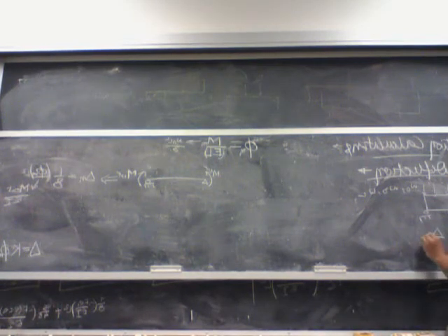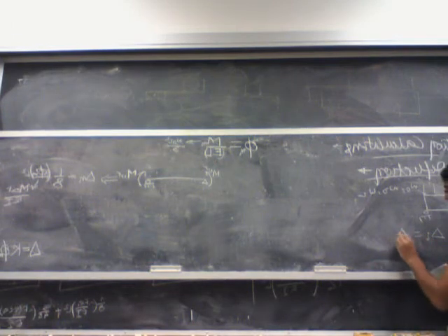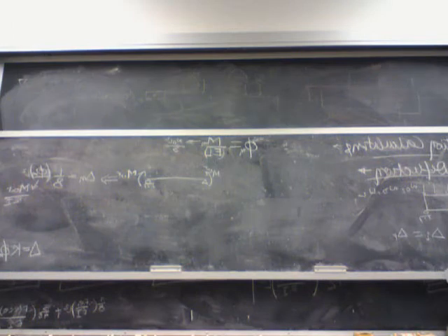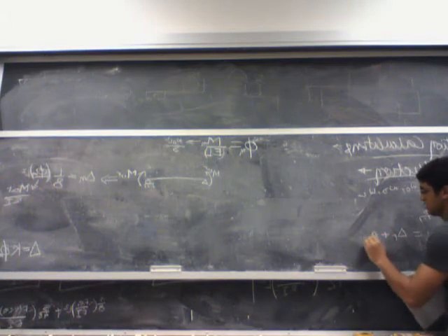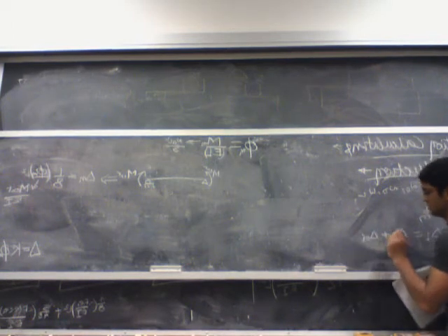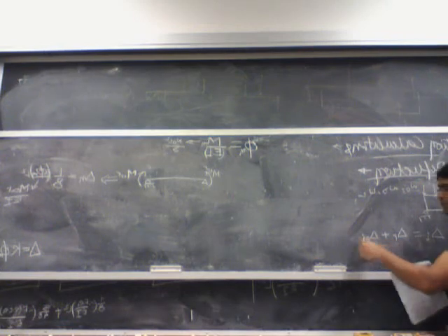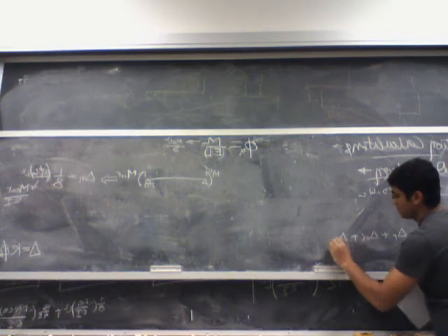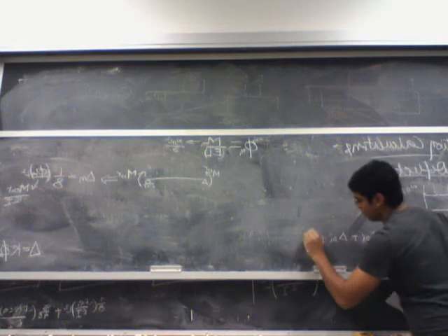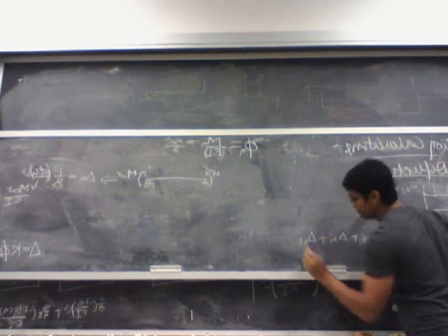So my total instantaneous deflection is the deflection due to the prestressing strand plus the instantaneous deflection due to my self weight plus the instantaneous deflection due to dead load plus the instantaneous deflection due to live load.